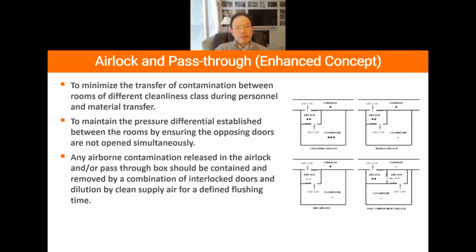You cannot prevent it, but you can minimize it. Close the first door, use the HEPA filter air to replace the dirty air, and then you can open the second door. So this ISO standard uses the term defined flushing time. In other words, the particles which migrated from outside into the airlock are removed before you open the second door. The time duration between the 2 door operations we call the flushing time.